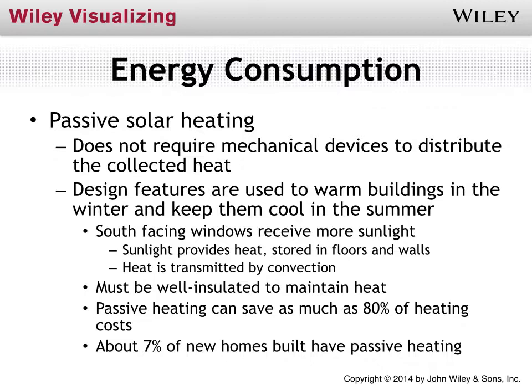The farther north you get, and the colder it gets, and the more days of cloudy weather you have, obviously, the less effective that's going to be. This is another area where we could do just so much more than we are. Only about 7% of new homes built have accommodations for passive heating. In other words, orienting the home so that a lot of it is facing north and south, large windows on the south side of the home, so that again you can take full advantage in the winter time.